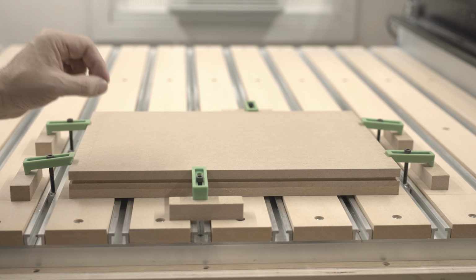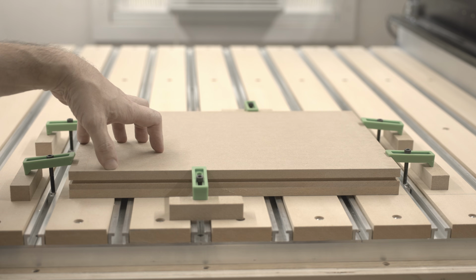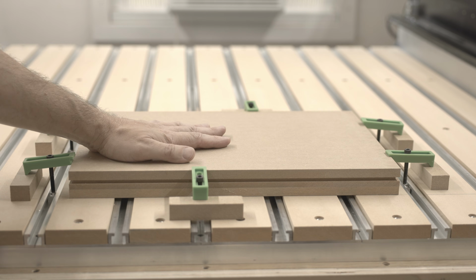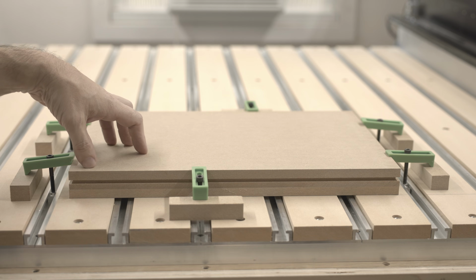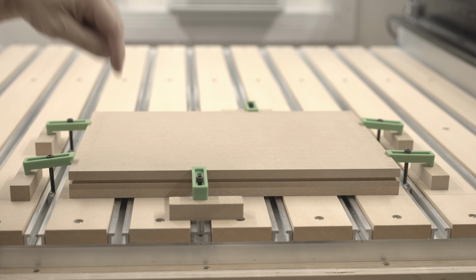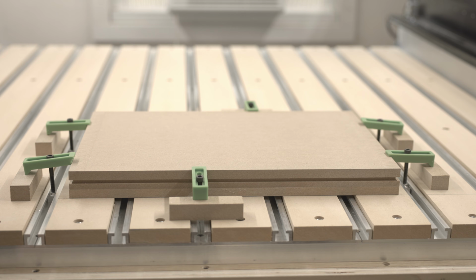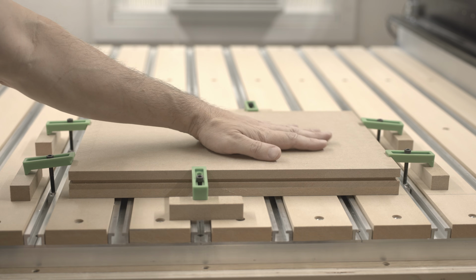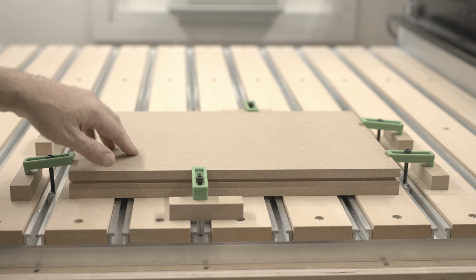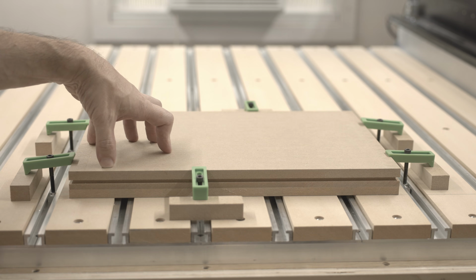are so minute that if your table is off or your board is off by, you know, even 5/1000ths of an inch, the depth of that cut is not going to be true or accurate, and the carving will not come out correct. It's going to look weird, okay? So that's why I'm stressing this. It's very important to make sure that you do this step.